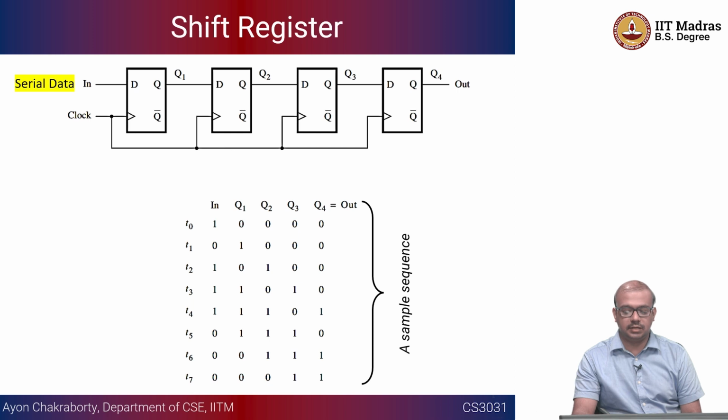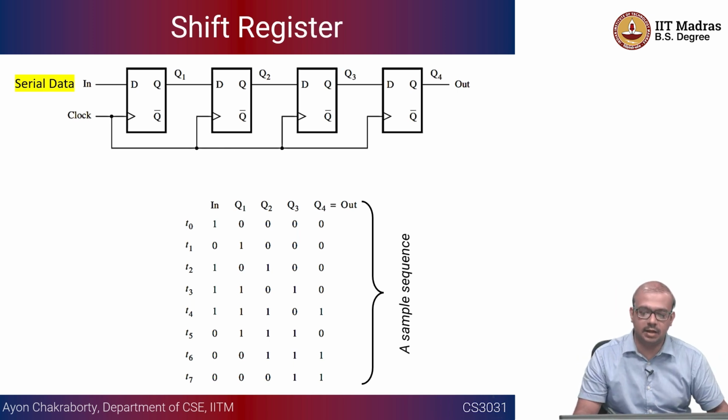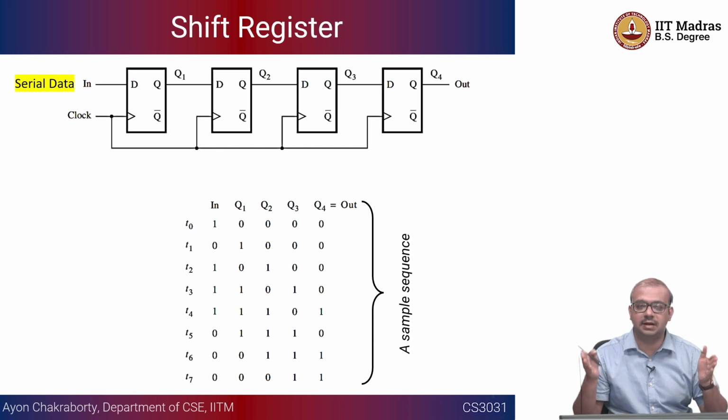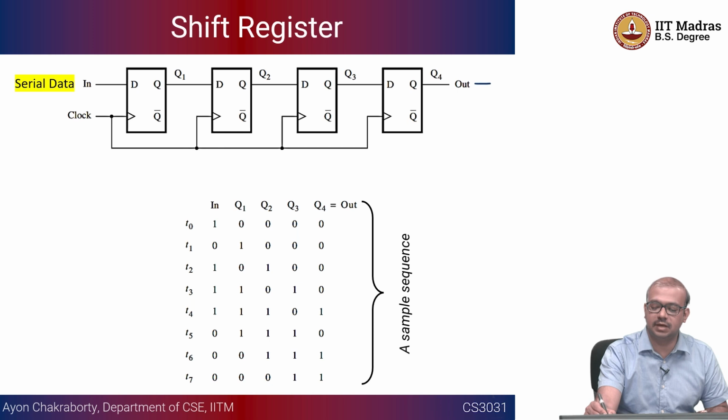So this is how the shift register is going to look. Because the data is coming in and being shifted, that is one kind of application where I keep on pumping serial data into the shift register. At a certain point of time, the shift register acts as a window of the serial bits that are coming in, and here the data is basically going out.